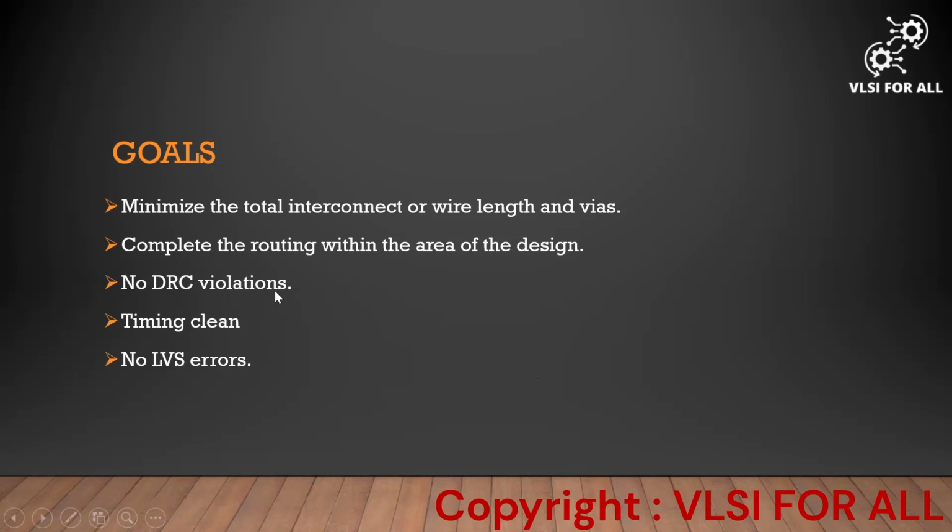No DRC violations. We have to make sure that no DRC violation is triggered in the routing stage. As I said earlier, timing also should be clean, and no LVS issues. You have to check this also, layout versus schematic, where we can see shorts and opens. Shorts and opens, if there are any floating routes, will be reported over here.